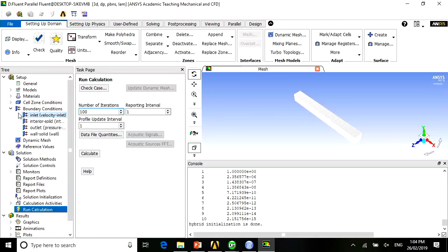It's running. So if you want to solve it as transient, there are sometimes CFD problems you need to solve as a so-called time-dependent problem. So you need to set a time step, right? Sometimes that is important because you don't know whether the flow is going to reach a steady state or not. And sometimes it's good to march the solution towards a point where it sort of reaches a steady condition. That means it could be a fluctuating flow, but it doesn't mean it's going to be a straight line. So sometimes you may need to solve the problem using transient to see whether it does exhibit a periodic manner, right? And that tells you whether the solution is actually steady or not steady.